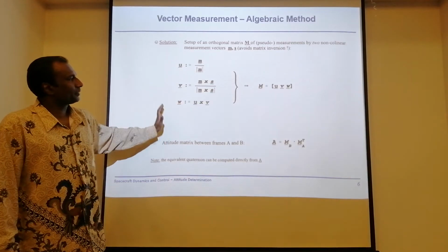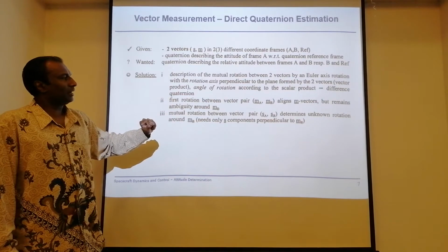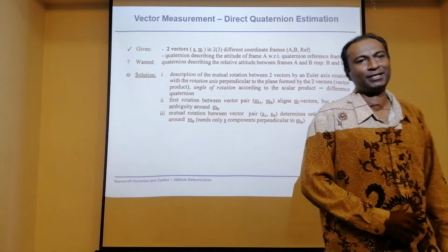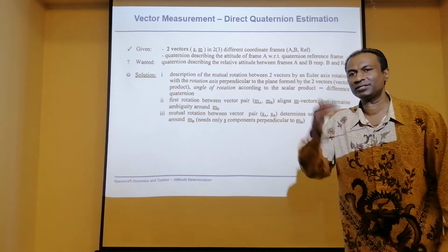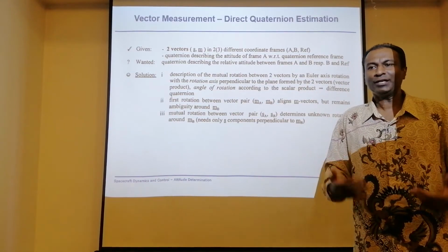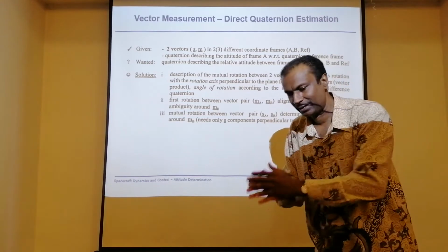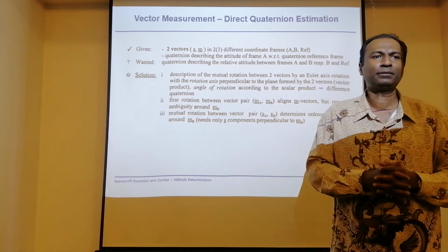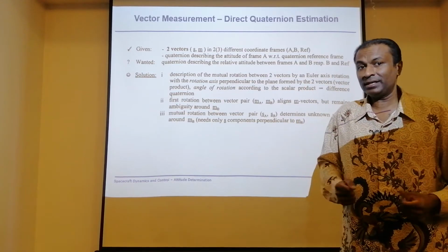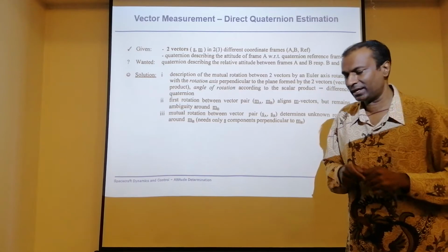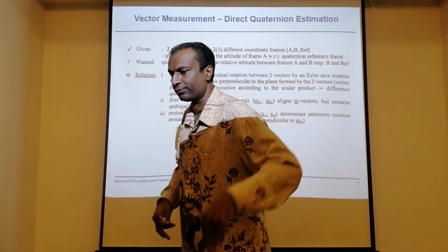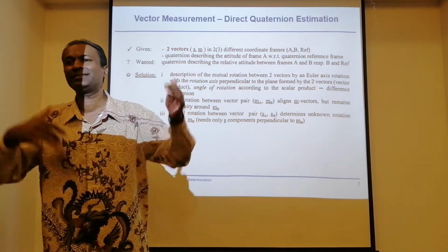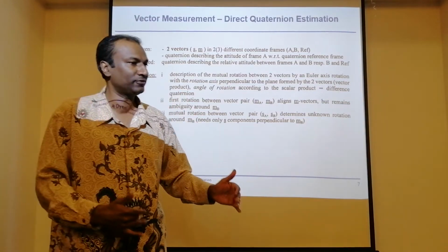Okay. Now, go on. We have also given you quaternions basically. The attitude information, the initial quaternion, is given as an attitude input. Then we ask you to express this in local vertical, local horizontal, or express this in body coordinate. We have also done that. So the deviation quaternion that we always talk about is the body coordinate with respect to local vertical, local horizontal. That is the deviation quaternion that we've always been finding.